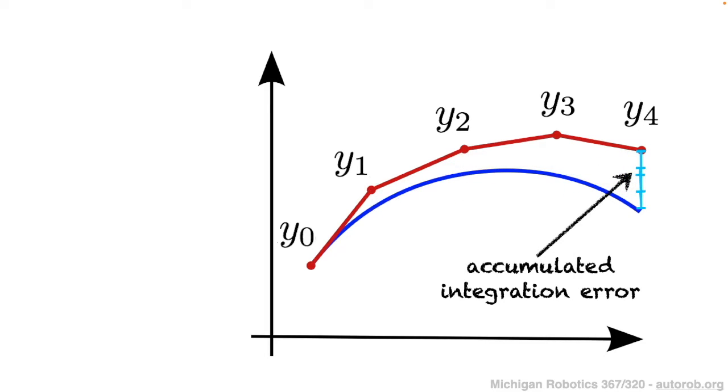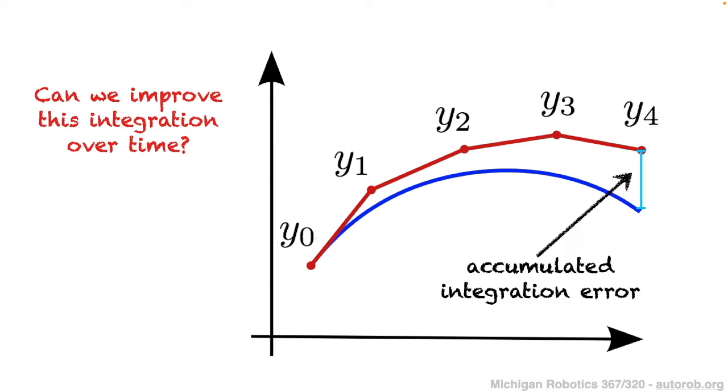And so you can see at the fourth time step, we've built up what is visually here a fairly substantial amount of error within our simulator. This is what we were seeing within the pendulum example, where the pendulum began swinging kind of uncontrollably, and it wasn't modeling the true state of the system if it had been following the equation of motion exactly. This motivates the question of how we can improve this integration in order to make our simulators robust and useful for modeling the robots that we're interested in.